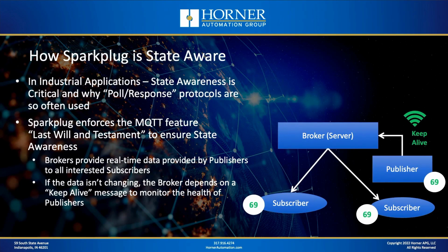Now, that data may not be changing very frequently, all right? It may only be changing, I don't know, every few minutes. So to manage bandwidth properly, but to still have confidence that the data is the latest and that the node is still online, when I log into the broker or the server, we agree that I'm going to provide a certain frequency of communications through keep alive messages.